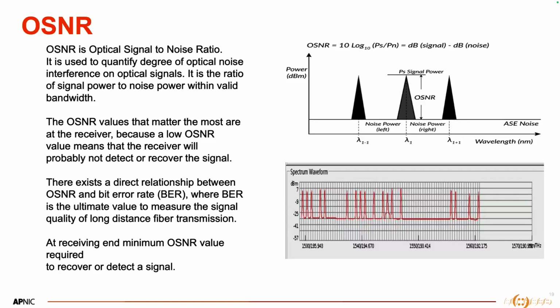You have to make sure that all the TX power of your lambdas have the same launching power, and your vendor will make sure of it. Because if you do not keep the launching power the same, when you do the fine tuning in the amplifiers or boosters, there will be a problem making all the lambdas the same level at the top to maintain a flat surface at the gain level.